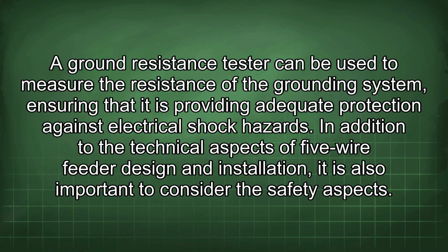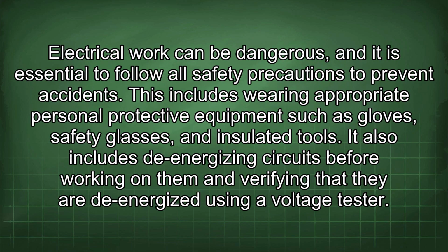In addition to the technical aspects of 5-wire feeder design and installation, it is also important to consider the safety aspects. Electrical work can be dangerous, and it is essential to follow all safety precautions to prevent accidents. This includes wearing appropriate personal protective equipment such as gloves, safety glasses, and insulated tools. It also includes de-energizing circuits before working on them and verifying that they are de-energized using a voltage tester.